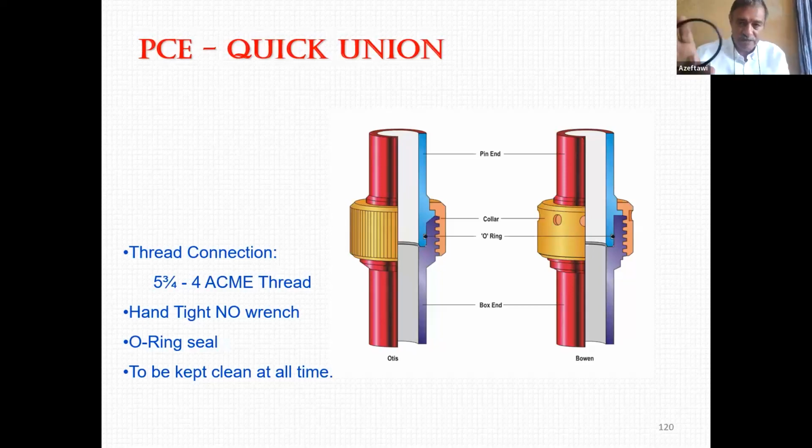One-time use. Look at this one in front of you. Look at that. It's really nice. It's black color, smooth surface, no tears, no cuts. It is flexible. I can guarantee you, if you reuse it, if you use it now, it will leak. Why am I sure of that? Because the life of this O-ring expired a long time ago.